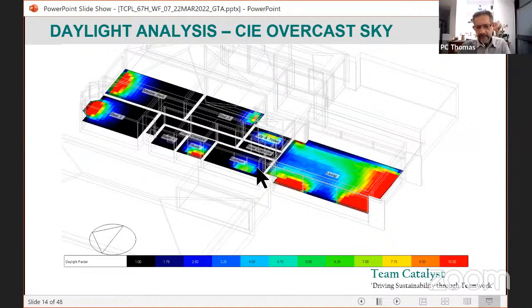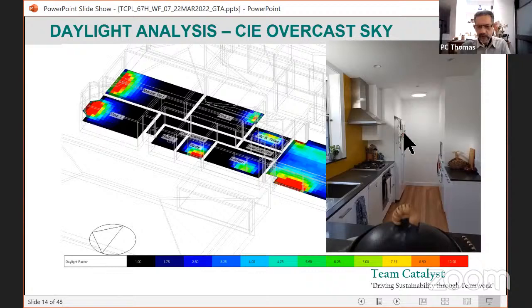This kitchen area, you can see very clearly. One side has got a window, so the daylight levels are pretty useful. But this part of the kitchen is dark. And so by just looking at that, you can take a design decision. And the design decision might be to put a skylight. So here's a post-construction picture with the skylight that's put just over there. And that obviously changes the way the building looks. You don't have to put any lights on anytime the sun is available.